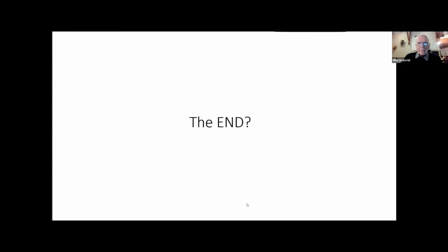The final question from Ian Simpson: if tablets are too big, could you use balanced antennas rather than ground planes to double the size of everything? I'm not sure I quite follow that, but anyway, I mean, probably too big. I think a balanced antenna is usually pretty big. There's just no room. That's the reason why you have very small antennas with big screens, because we are using the ground plane as effectively the radiating element. That is the radiating element, to be honest. It's not the little antenna at the top. That's just an exciting element.